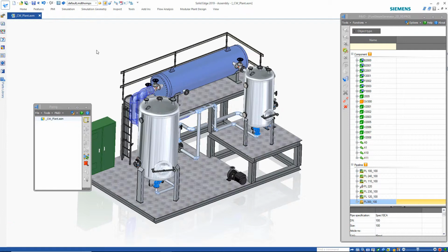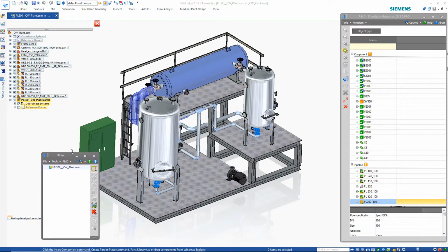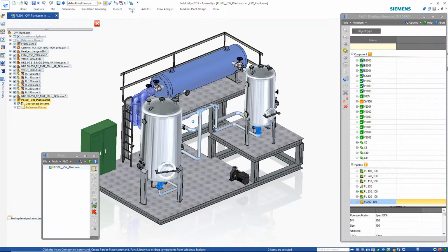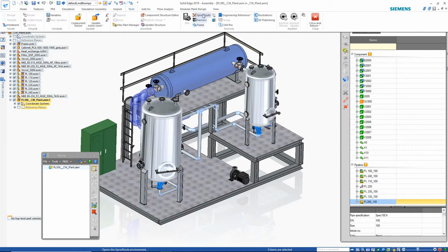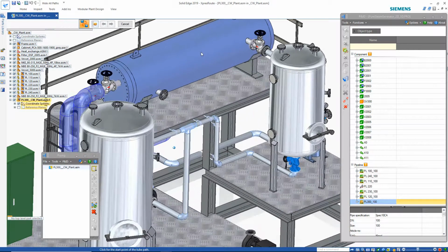After in-place activating into the new subassembly just created, Solid Edge's Path Express will help us quickly create the desired pipe path from the same two ports highlighted earlier. Path Express can be used to create the actual path between the two connection points.